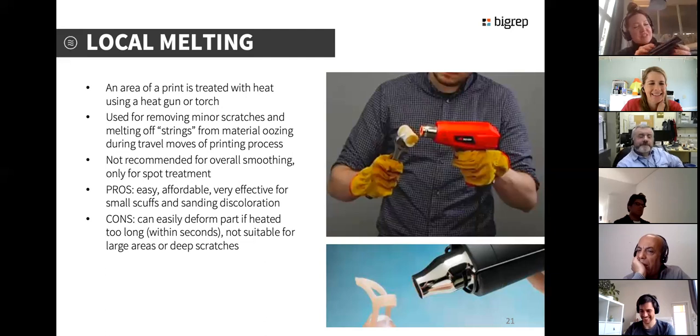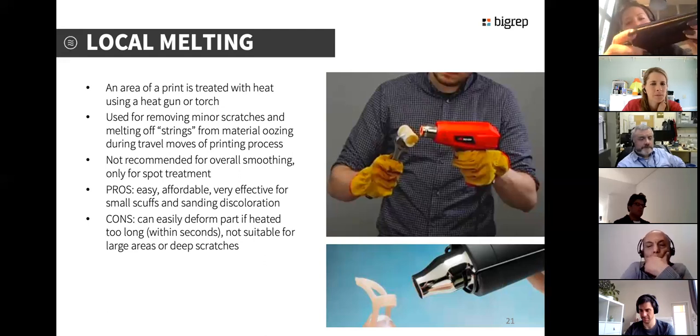But normally I would just take a heat gun or this little torch and hit this here. With dark prints, if you sand them, they lighten, and that will pretty much take away some light scratches. It's really effective. Like you can see here, this edge is kind of rough. If I hit that with the torch here, that'll all go away.